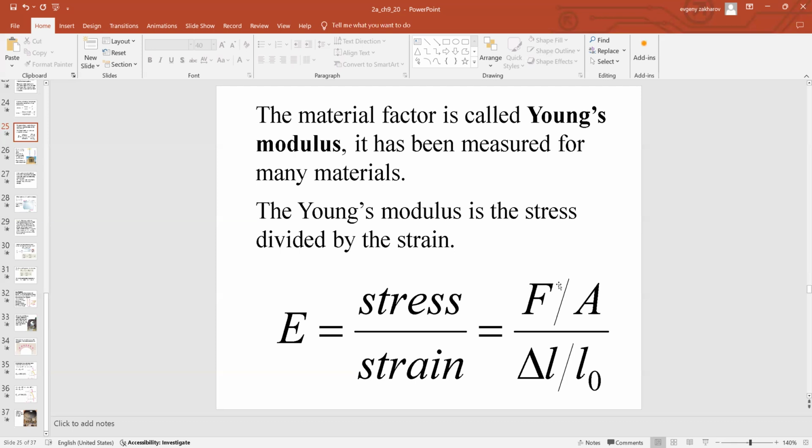And then you can either calculate the force that is needed or the elongation that the force produces, doesn't matter. So force over area, elongation with respect to the original length or width or height. That's all you have to do. Literally, that's it. End of story. Nothing else from elasticity. The simplest possible scenario right here.